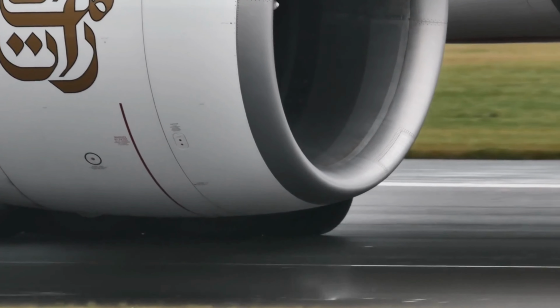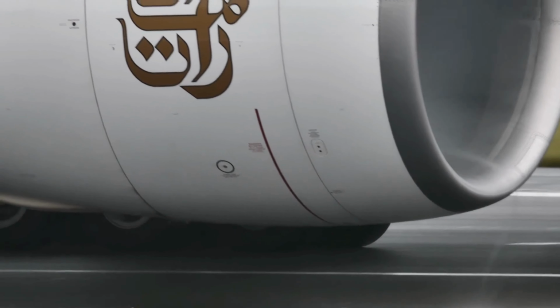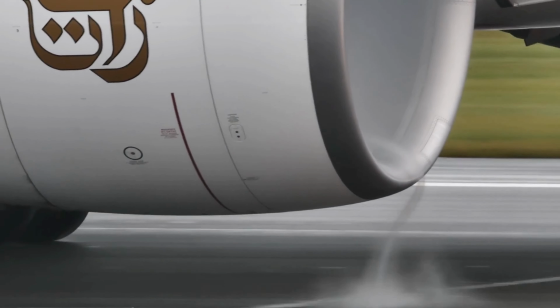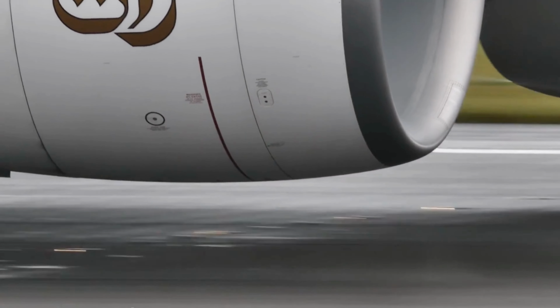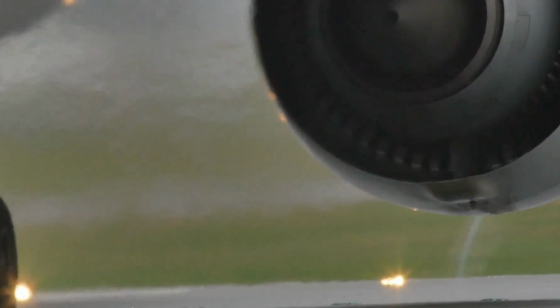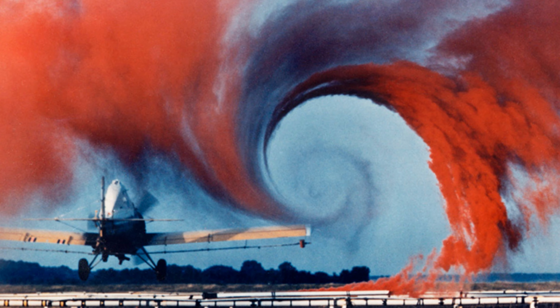Another area where there's a big pressure differential is at the fan blades of turbofan engines operating at a high power setting, such as on takeoff. If you look inside the engine intake during a takeoff run, you might see condensation fog inside the engine intake if it's humid enough. Propeller and rotor tips are another area where you might see contrails formed by tip vortices, although they look like a series of spirals instead of straight lines.